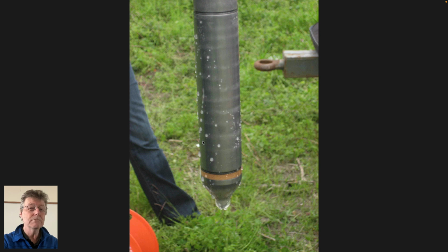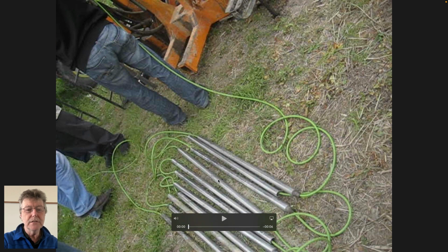No? Well, it's a condom. Okay, fine. So this is a condom that's put on here to be able to saturate the frit here with silicon oil. It's usually boiled in silicon oil to be able to get air out of this solution, so that when you put it into the ground, it's fully saturated with no air in it, which affects the pressures that you measure. And then you place this into the ground.